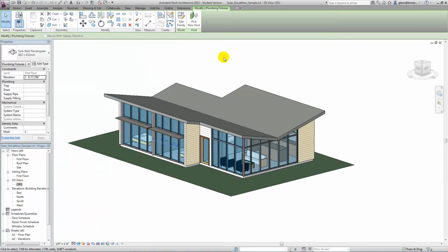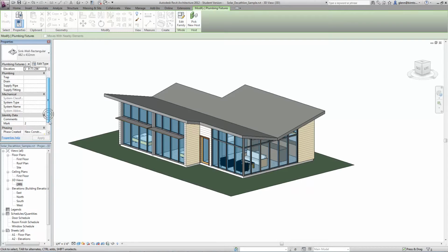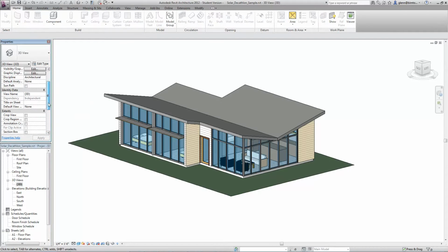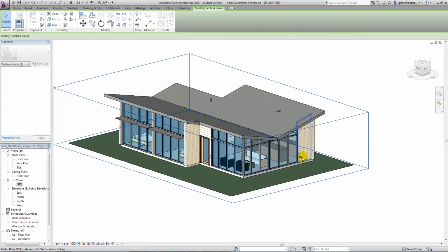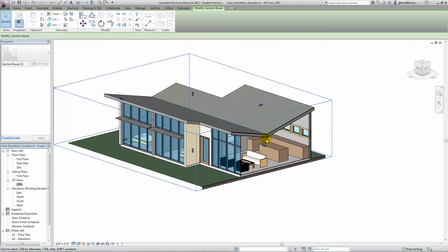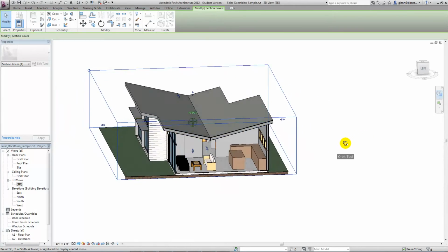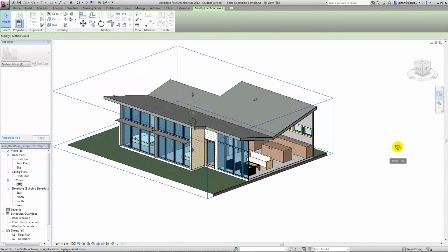Now, these models also are very good for doing things like visualizing, so let me show you here. Even in a very basic sense, we can do things like open up something called the section box, which lets me create dynamic sections, so I start to conceive about how the building's actually constructed and what the elements are inside. Okay.